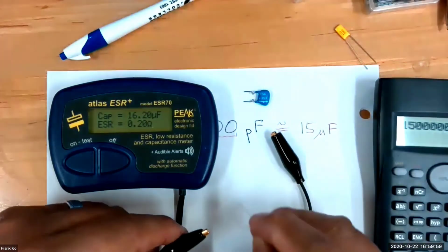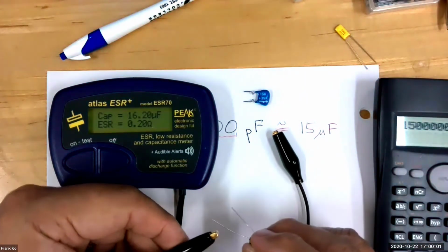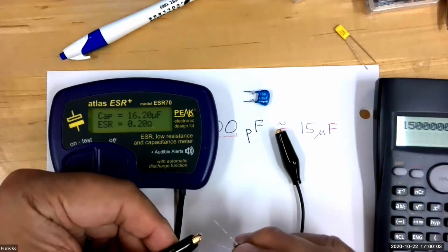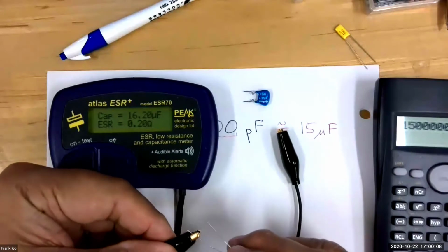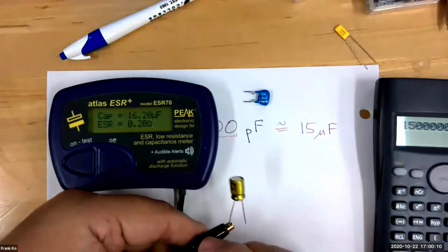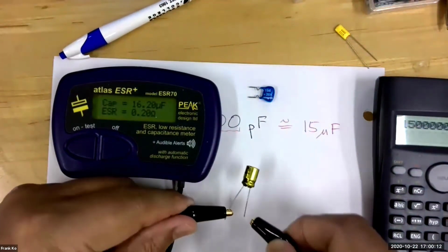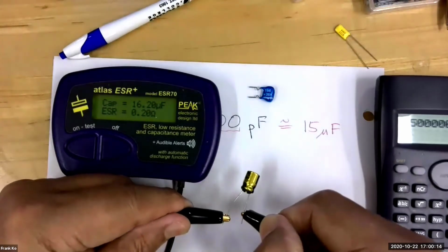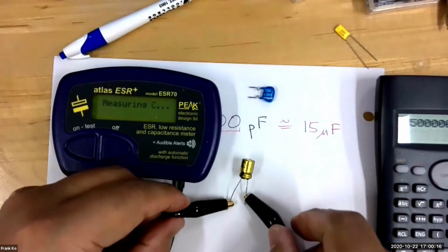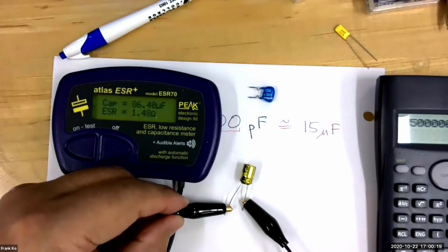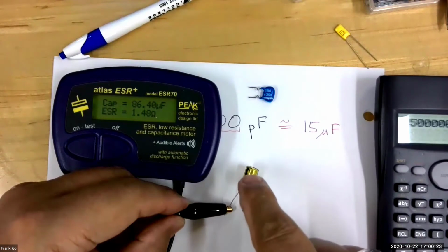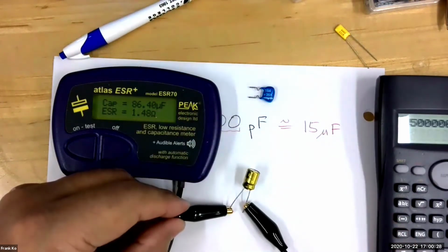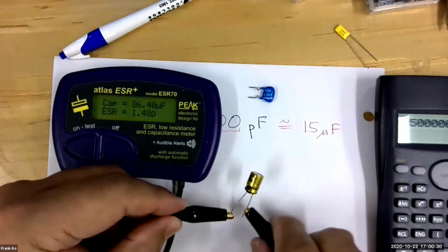This one here, the body of this guy is coded at 100 microfarads. Go ahead and hook this guy up on this lead. Come on, alligator, here we go. And hook up this lead over here. So it's coded 100. I know this one didn't measure 100 because I did this earlier. It's still microfarad, so it shows us the appropriate scale, but instead of 100 microfarads, what's this come out to? 86.40. That's quite a ways off.